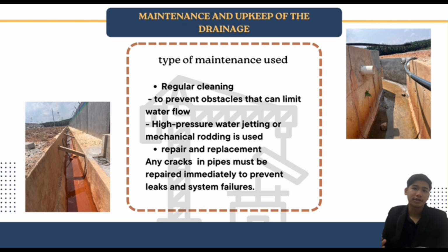High pressure water jetting or mechanical eroding was commonly used in this cleaning service to remove silt and debris from pipe and channel. So preventive approach such as installing leaf guard and sediment trap near entry point was installed in this drainage to prevent it from clogging problem.